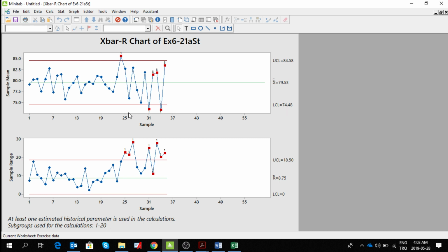So let's look at that. We have number 24 out of control limits, and also 31, I think 32, 33, 35, I guess. This is sample 34, test 1 failed. So we are gonna mostly look at test 1. These are probably test failures. It is sample 32. It shows the test number here too. These are all test 1 that failed in the R chart.